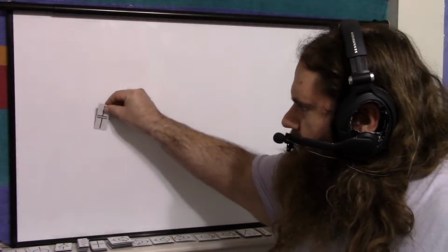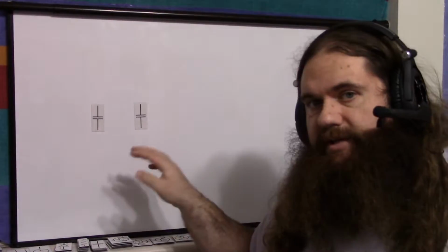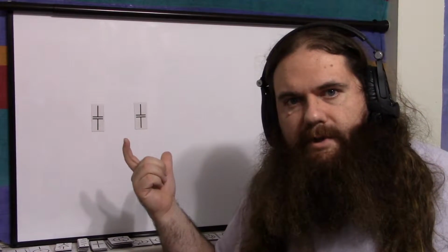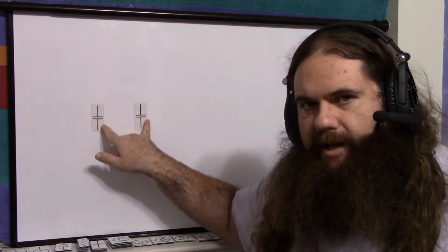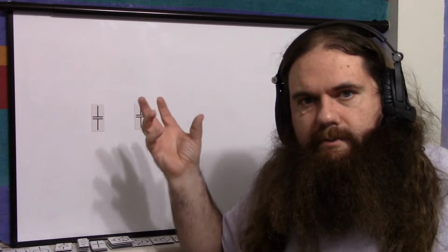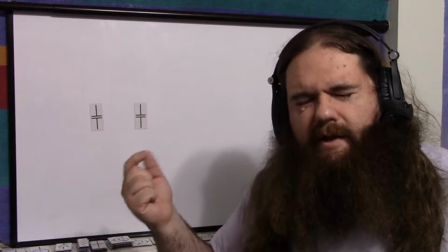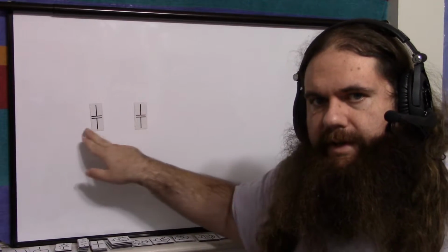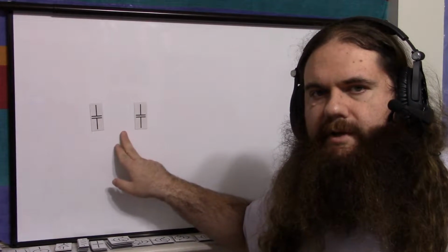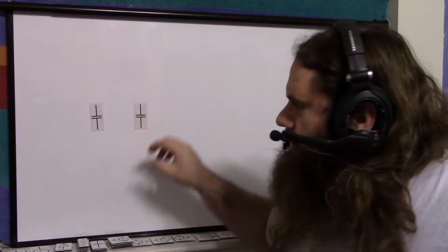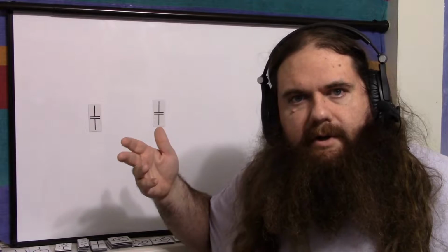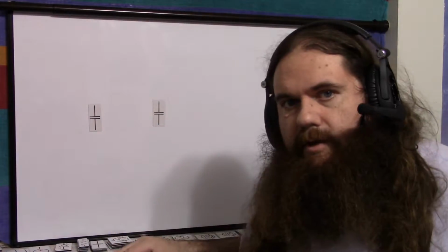So the idea behind capacitors in parallel is that they conceptually share the surface area of their plates as if they were just a larger capacitor. So you add the capacitances and you have this parallel part behave as if it was one bigger capacitor. The equalization over them, if they have a different voltage on them, it equalizes based on charge over the surface area. I go into more detail on this in the two capacitor paradox video, so watch that. Here I'll do a quick review.